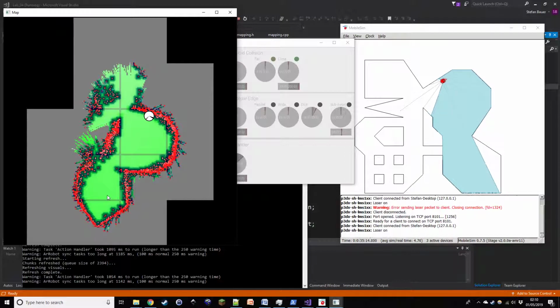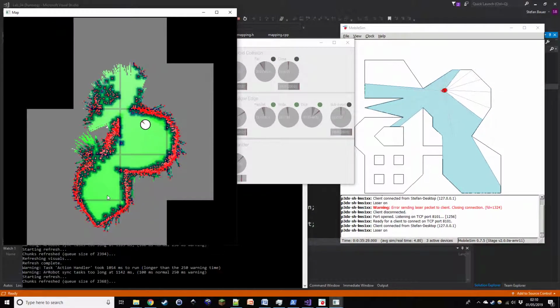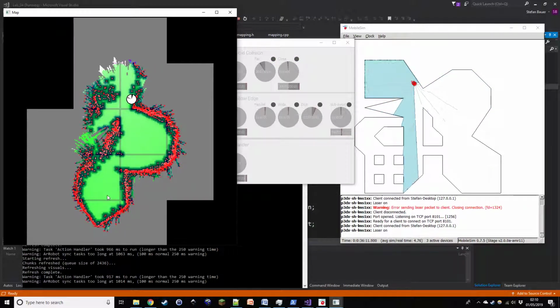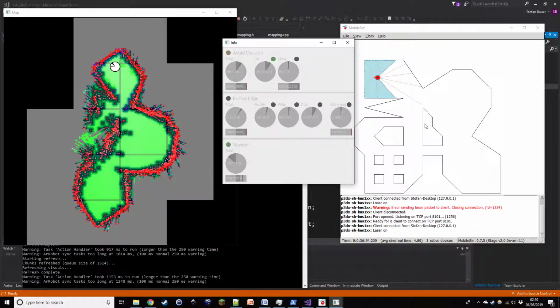This, in addition, has a weighting such that theoretically it weights unexplored areas that are closer to whatever the set map goal is. And then what happens is for the wander behavior, it simply takes the pixel that the robot is currently on and works out a gradient based on its neighbouring pixels. And then it tells the robot to go along that gradient after normalizing it. And theoretically, the robot essentially just runs downhill, it treats it like a height map, runs downhill to the nearest unexplored area.